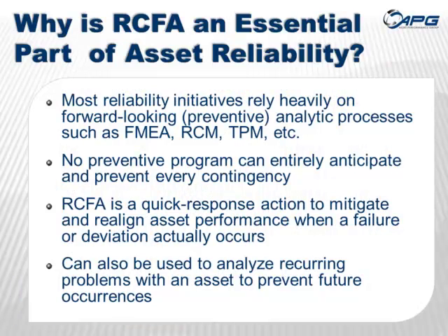So why is RCFA an essential part of asset reliability? And I think to me this is really the essence of it. Most reliability initiatives, in my experience, rely very heavily on forward-looking preventive analytic processes such as FMEA, RCM, total productive maintenance, etc. And so they should. Of course, we're ultimately trying to prevent future failures and increase uptime and all that good stuff. But RCFA adds an essential and necessary element to reliability programs and practices because no preventive program, no matter how proactive or well-designed, can anticipate and prevent every contingency.